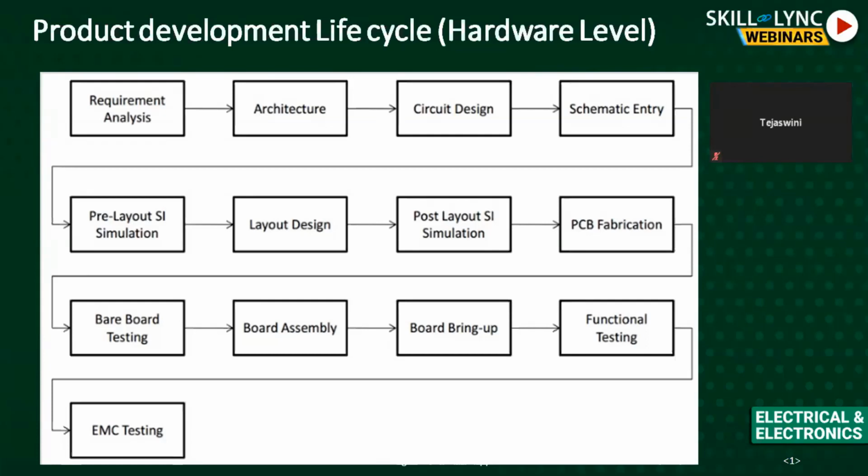So I cannot suddenly load the software. First, I have to check the power supply, and then I have to check the functions, like different GPIOs, whether they are working. So each section of the board is powered up and then checked. Finally, the function testing. Finally, the actual software is loaded on the board, onto the controller or the processor, and then it is checked. And the EMC testing. This is really important nowadays, because the product, whatever you have defined and done, should function in the EM environment, the electromagnetic environment. So this is very important nowadays.